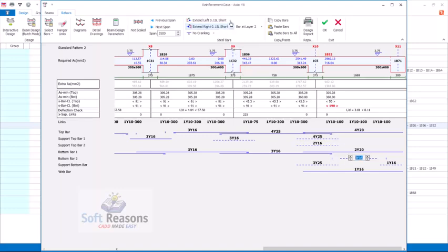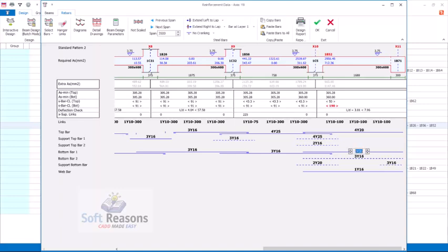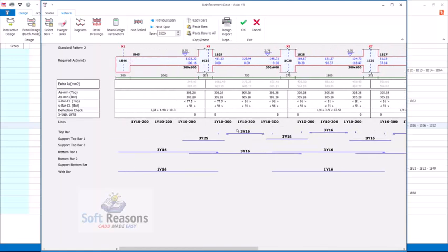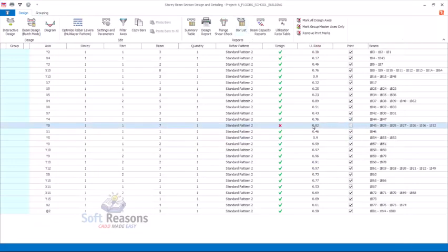I think this space issue is from these provisions. You can extend this to the slab, and extend this to the slab as well, just like this. And then over here, this sign has to be removed. You can increase this reinforcement to 3. Okay, you can see now we have that sign removed successfully. That red sign is gone. Okay, so with this, everything has passed the design successfully. Click on the OK options. Alright, so one thing in Prokon Structure: when a beam has failed and you have corrected the failure, you have to refresh it.